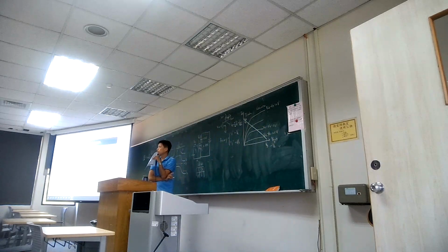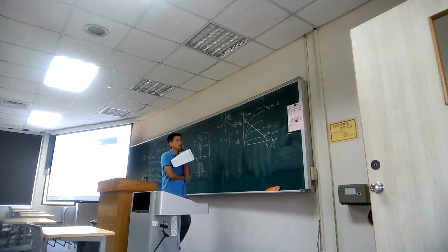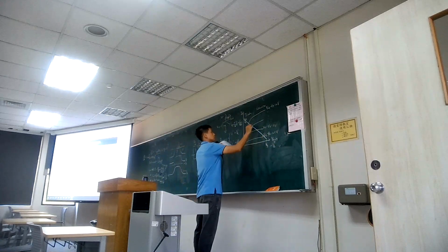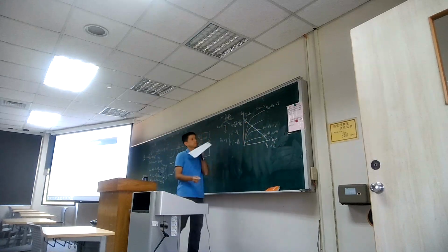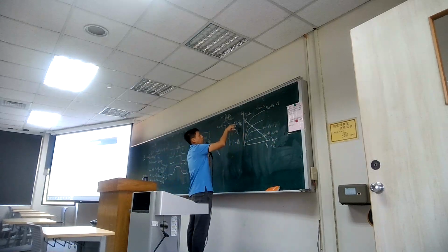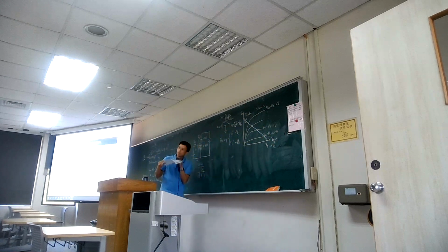When you connect this MOSFET transistor with RD and then bias the current like this, that is what happened. And the cross section region is the solution. So here's the solution. And then you can see what is the slope. The slope, you can take this as y, so you get this VDD as the output over RD. So it's 1 over RD. Right?